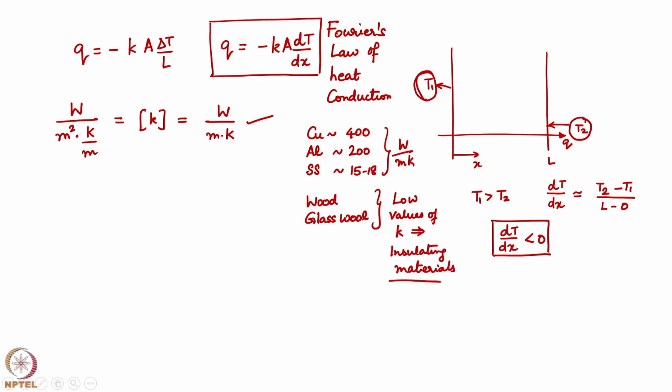Okay, so this is Fourier's law, this is conduction. And what do we say? dT by dx, we'll see later on, we would have a temperature drop which is linear. So this is a temperature variation, dT by dx would be negative, and in Q by KA, A is the area normal or orthogonal to the surface. So for two walls, this is the area for heat transfer. Okay, next we come to convection.